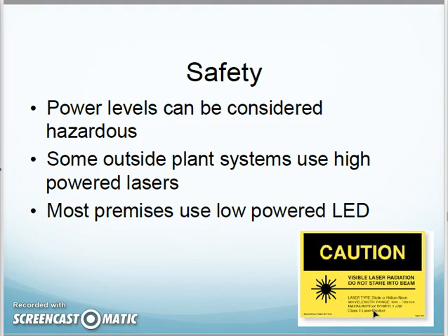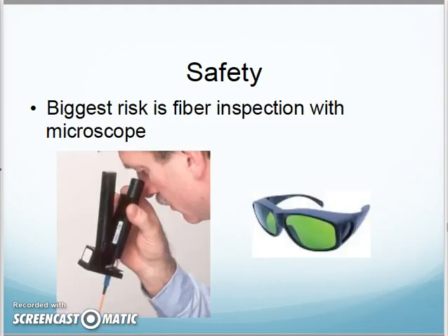They remind us on safety. Yes, with fiber optic, you do have light sources, some strong light sources, and even some laser light sources. So they remind us that some of the light sources we deal with could be very strong, especially the outside plant. Premise uses low-power LEDs, but your outside plant might actually use laser. So we have to be careful of that, because that can potentially do eye damage. They do make special safety glasses that are designed to shield your eye from that.